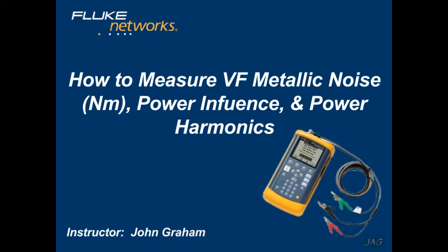Noise on copper pairs can come from a variety of sources. One of the most common sources is power line interference noise, due to the simple fact that telephone lines are very close to power lines. You can use the CopperPro to make several measurements that will allow you to determine whether or not a pair is suffering from power line interference noise problems.